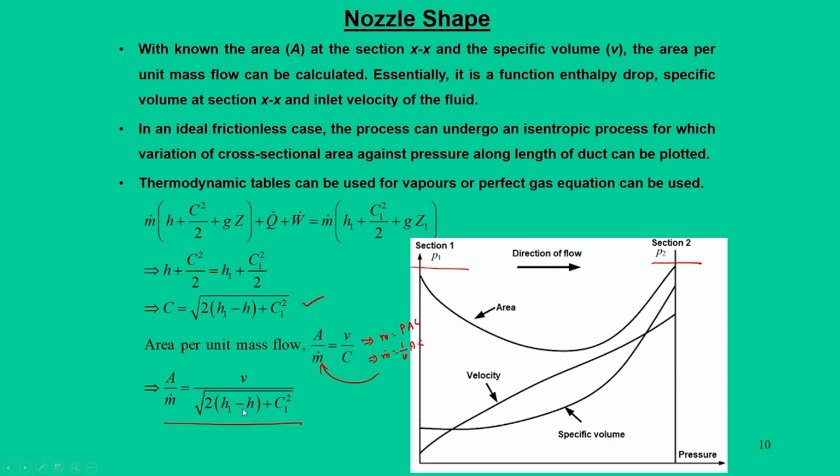And remember, we are using fluids, either steam or liquid. The generic graph shows that with decrease in pressure, that means when we perform the nozzle action, the area drops down to a particular value and then further increases, and the velocity continuously increases, which is our expectation: velocity must increase as pressure drops.